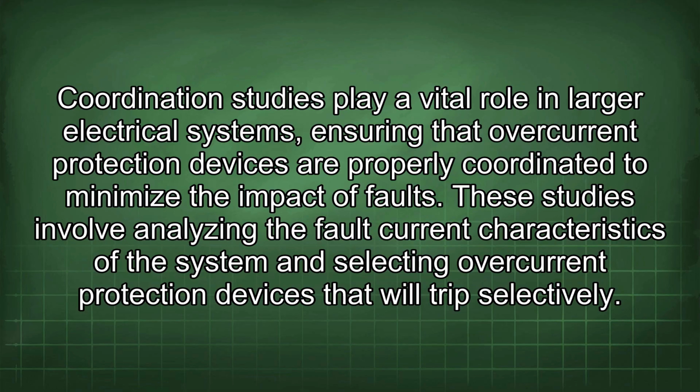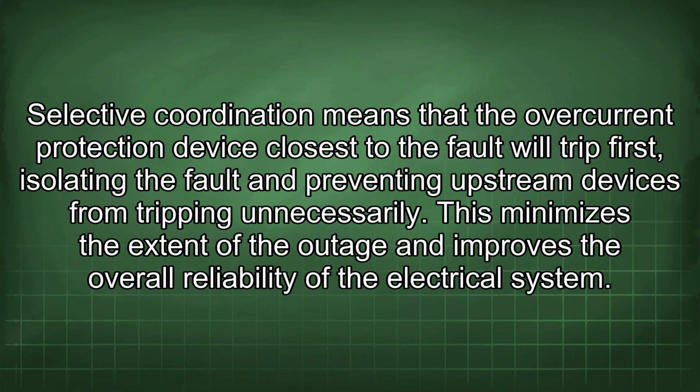Coordination studies play a vital role in larger electrical systems, ensuring that overcurrent protection devices are properly coordinated to minimize the impact of faults. These studies involve analyzing the fault current characteristics of the system and selecting overcurrent protection devices that will trip selectively. Selective coordination means that the overcurrent protection device closest to the fault will trip first, isolating the fault and preventing upstream devices from tripping unnecessarily. This minimizes the extent of the outage and improves the overall reliability of the electrical system.